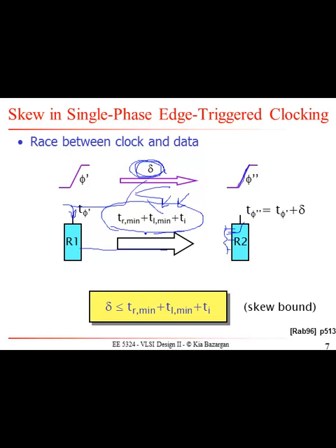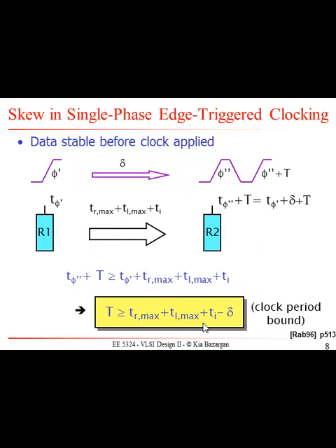And if you think about adder, again, look at the least significant bit. It only needs to go through a few gates, and it is not unreasonable to assume that you will have race conditions. So basically, if you put 2 plus 2 together, you would figure out that your delta, the amount of skew that you have on your clock, has to be less than or equal to this minimum value, right? So no data should arrive sooner than that delta.